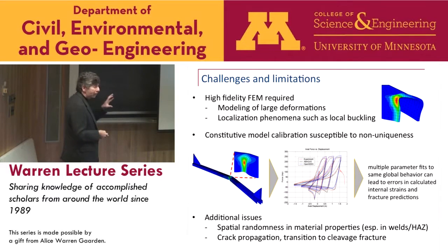We've just really looked at fracture initiation, and as you saw in some of those examples, real bad things don't happen until the crack grows far enough. So we haven't taken this to the next stage to really apply them to crack propagation, and also then to look at the transition to that brittle cleavage fracture. Is it as simple as saying, you have a critical crack length, and when the ductile crack goes that long, you transition to brittle cleavage, or is it more complicated than that because you are deforming this material?